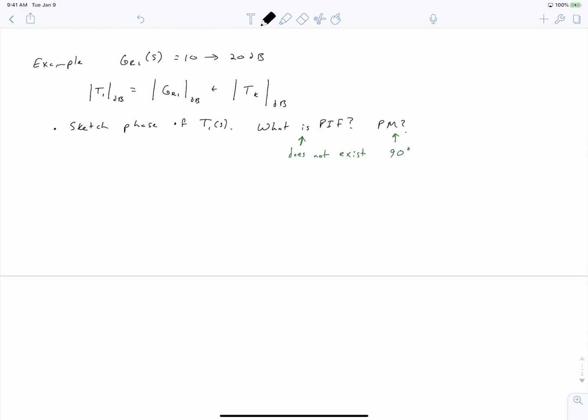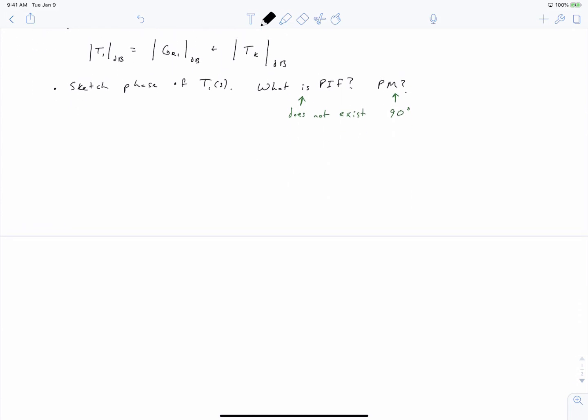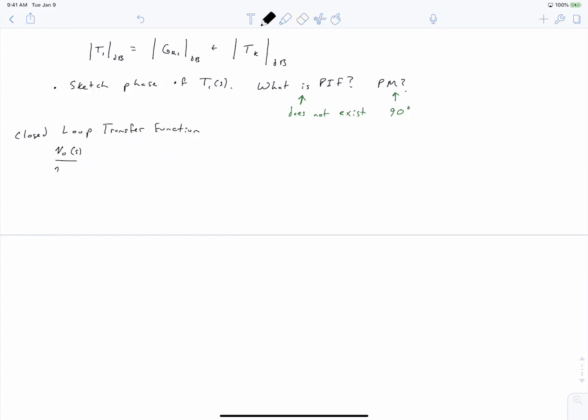So let's try to develop some theory to analyze whether or not the gain is sufficient in the low frequency regime. So again, we can talk about this through our closed loop frequency response transfer function, where we'll specifically just talk about this portion of it, which is again 1 in parallel with T of S. And we want this portion to be equal to 1.